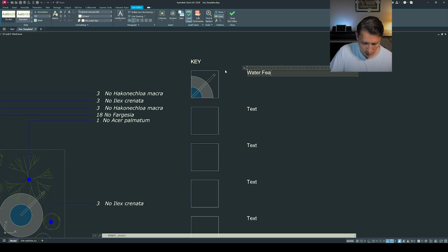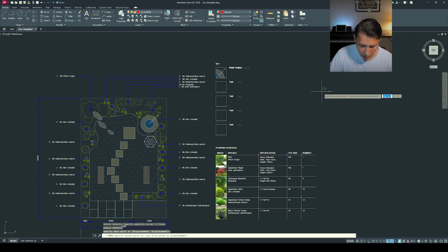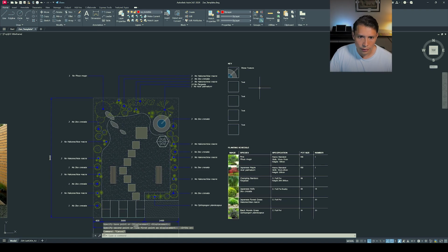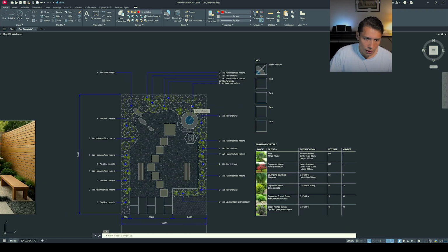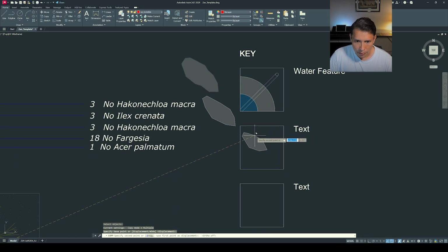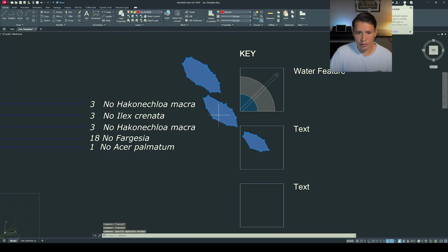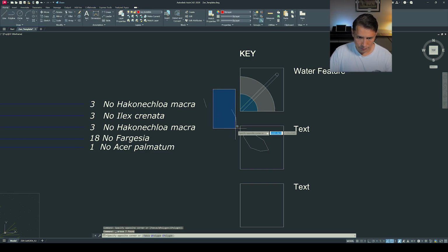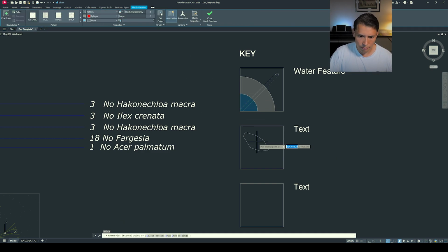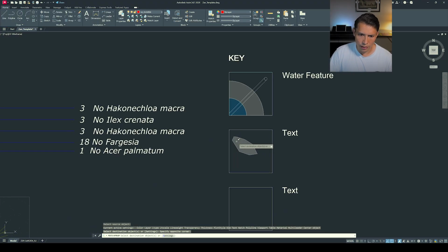Water feature. Then I think we can move this text closer to the key, probably somewhere there to see it closer. And this one as well, probably only one will fit. Press ortho and deactivate the ortho, then you have the stone right there. And because this hatch is linked to the three shapes, we will need to basically do it again. Delete that, press hatch, click inside here, and then copy the properties, rock hatch to here.